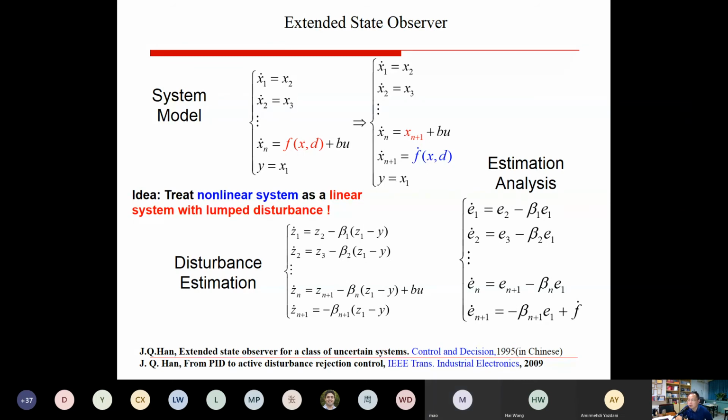The first thing is you have to perform a system analysis. That means you have to connect the data, you have to see your model, and also consider the influence of noise. You have to model your system well. If you just use PID and your hardware is not changed, or you do not have a hardware solution to improve it, all you can do is use a control algorithm.